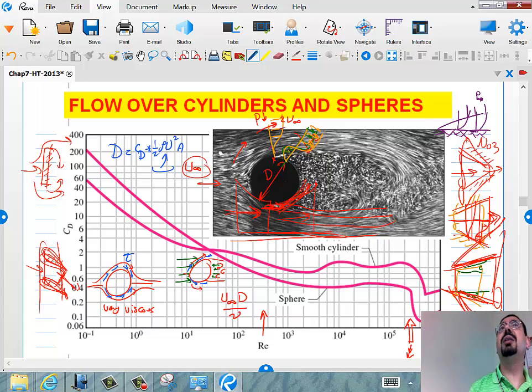So as a result, the same pressure ratio from 10 bar to 1 bar, I can make it in 3 nozzle plates because I can squeeze them through a huge area reduction and finish the whole 10 bar into 3 plates. But on the compressor side, I cannot make him go from 1 to 10 bar immediately. I have to be very patient. I have to make the area change really, really slow. The area change across the diffuser cannot be huge.